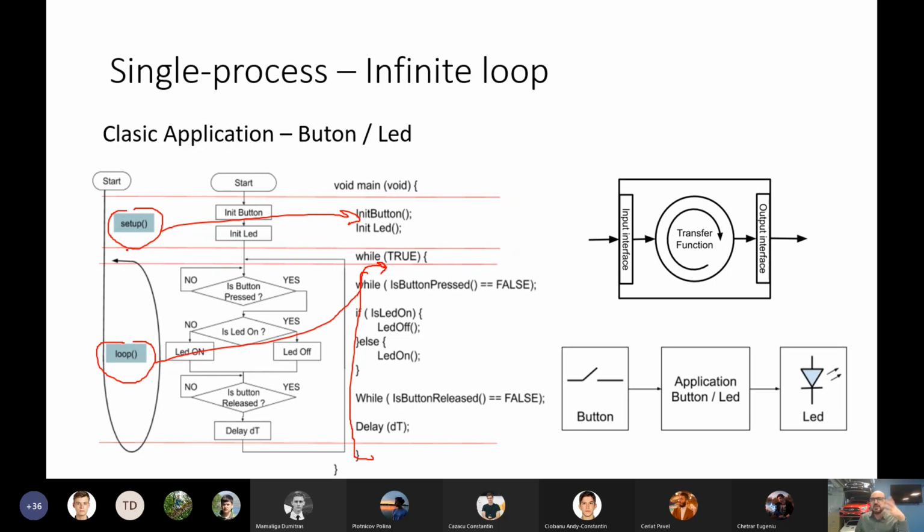It's a kind of foolproof protection, because usually beginners don't know what it means to program a microcontroller in C, and they need some simpler methods. So the Arduino defined the function setup, where they say: everything that you want to start from the beginning, from the power on, you put inside of it, and everything you want to be executed in a loop, put in the loop.